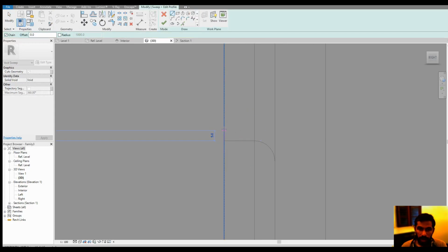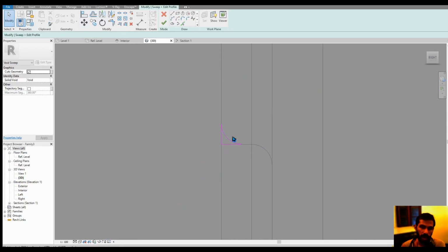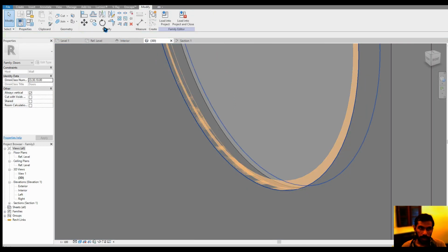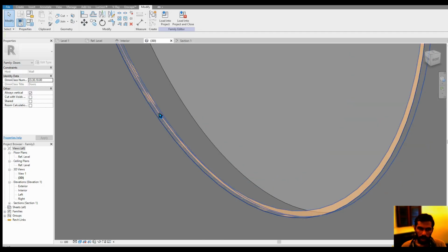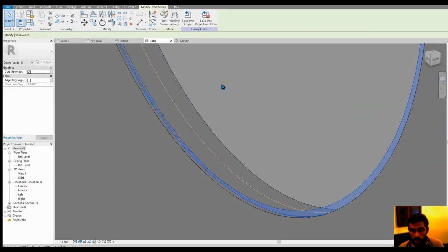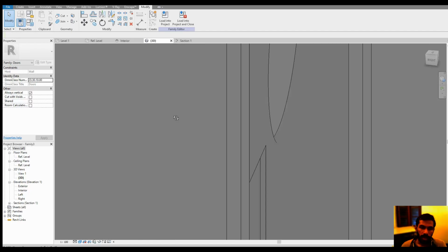Make sure that the length of the line in both directions is the same, 10 here and 10 here. Okay, now let me try to start, and the radius should go inside, so where you want to have the fillet, that's showing up the direction of the radius. Cut, and you can cut it as usual, and I'm not going for that.